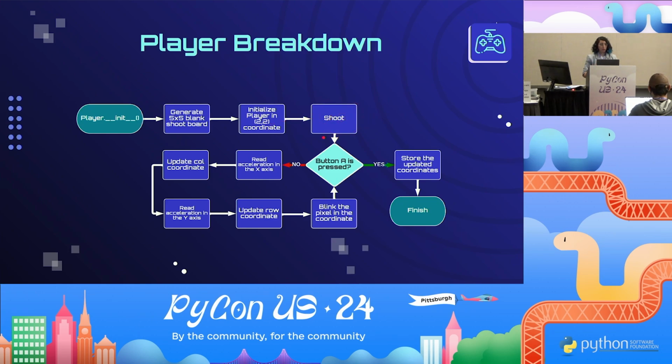And then we are going to shoot. So we check if the A button is pressed, which is how you make your shot. And we check the acceleration in the z-axis, in the x-axis, and we update the coordinates in the column because of that difference in the indexing that I mentioned before. And we do the same thing for the y-axis, and we update the row. And we are going to be blinking the pixel in the display so you can see where the pixel is positioned. And after that, we are going to be checking if the A button is pressed. If it's yes, we store that coordinate, and that's it. You have updated the coordinates for the player.